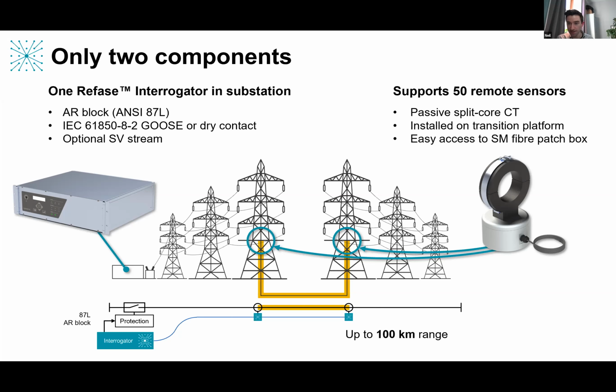Of course, and it is an important differentiator to say that we're not a wireless technology or an IoT type device, which would require, as you say, batteries and things like 4G access in order to communicate measurements. Those can be susceptible to the battery failing, so you need regular maintenance, and there are various security concerns about using wireless transmission as well. So what we do with our sensors is we splice them, we hardwire them into the existing optical fiber in the network. We would take a fiber from the OPGW, one end would go into our interrogator on the left-hand side of the screen here.